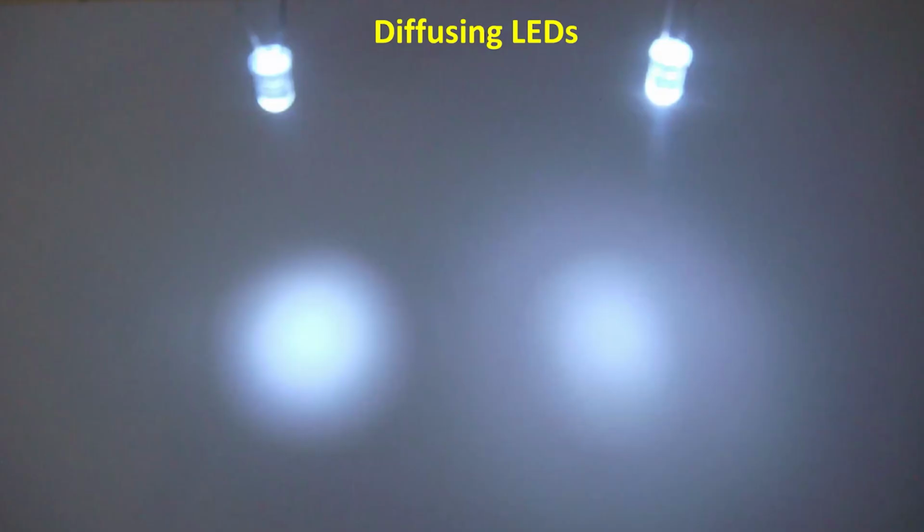Like that. There's two examples. The one on the left is a standard white LED, and it gives you a spot of light, a pool of light rather than even light. And what I've done with the right-hand side one is I've got a small file, and I've filed down the front bevel of the lens. And the effect, as you see, is that it distributes the light much more evenly.